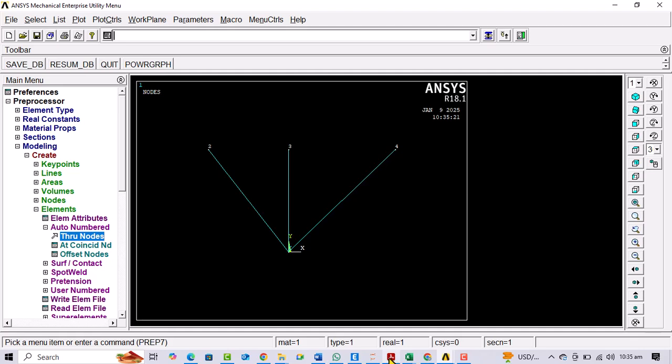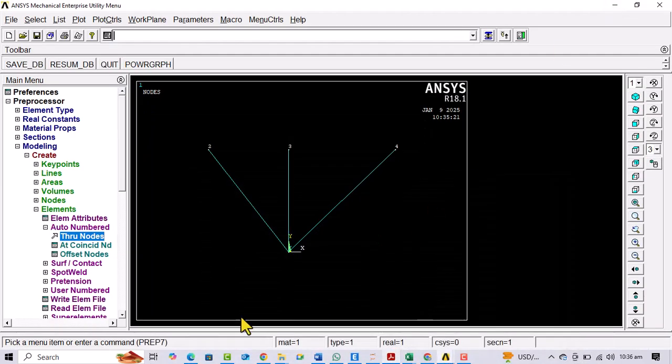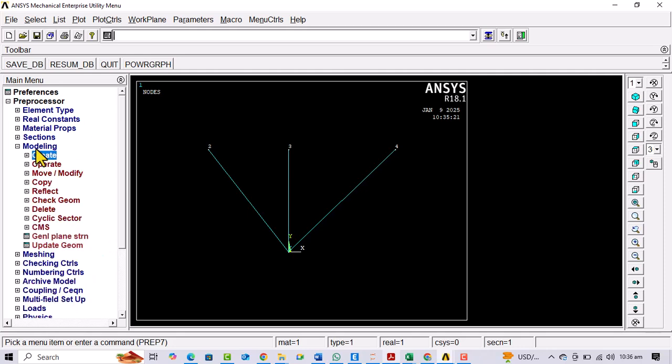After that, you see that we basically have a hinge support, meaning restriction in the x and y direction, but we can consider it as a fixed support because we are working in 2D, so that will be automatically restricted. And here we are seeing that there is no support, instead forces have been applied. So what we do, we will simply go here, and for node 1, now I will be closing the